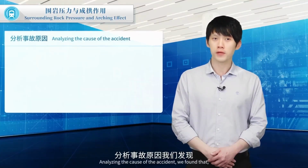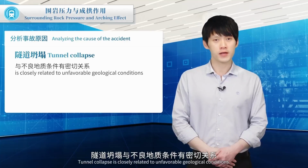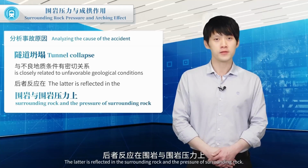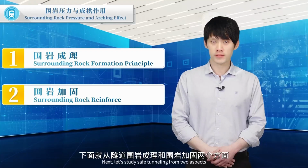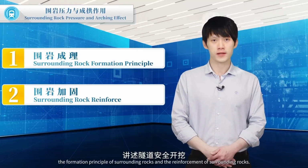Analyzing the cause of the accident, we found that tunnel collapse is closely related to unfavorable geological conditions. The latter is reflected in the surrounding rock and the pressure of surrounding rock. Next, let's study safe tunneling from 2 aspects: the formation principle of surrounding rocks and the reinforcement of surrounding rocks.